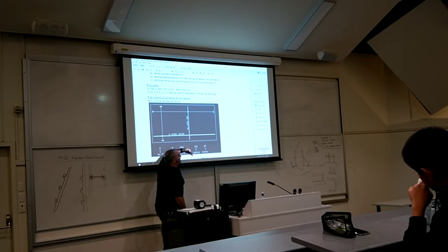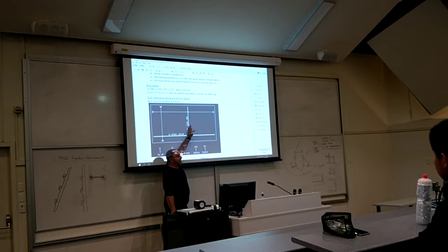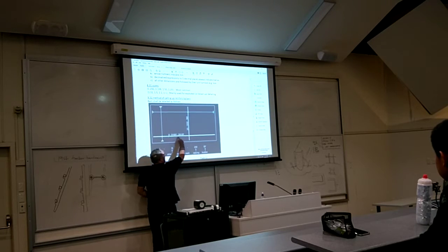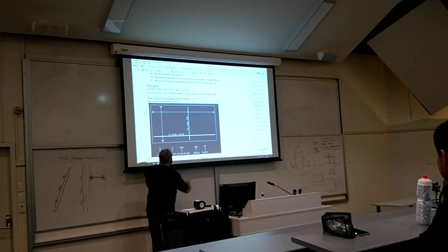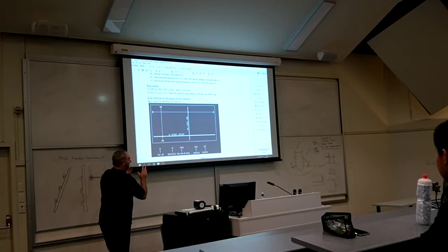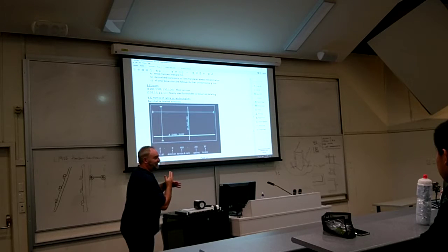Right? Now, please take note. That is on top of the bar. That is on top of the bar. It's not on top of the reinforcing line. It's not way down here, which some students do, with an arrow to it. All right? It is on top of the bar. Now, that looks pretty straightforward. There are only 2 bars going in 2 directions.